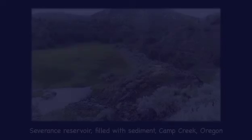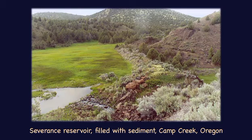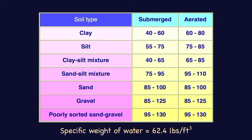Drying or aeration of a sediment deposit helps to accelerate consolidation through removal of the water from the pore spaces. This table shows the effect of aeration on the specific weight of sediment deposits in pounds per cubic foot for several types of soil mixtures. Note that the specific weight of sediment deposits can vary from about 2/3 to more than twice the specific weight of water.